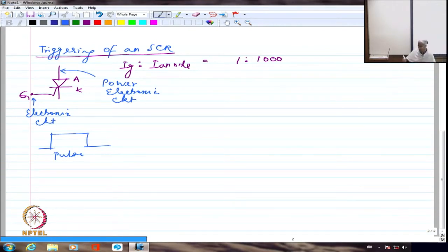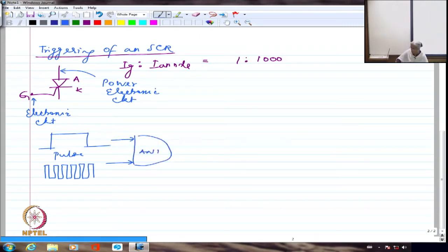So what we can think of is like a clock in your computer or microprocessor. I can have a clock, this high frequency pulse, and the normal pulse. Both of them can be given to an AND circuit, AND gate. So if I do that, whenever I'm going to have this pulse, I'm going to get essentially the output of this to be, all here it will be 0, and then I'm going to have some pulses like this. This is how the pulses will be, right? This will be the output of the high frequency ANDed circuits.